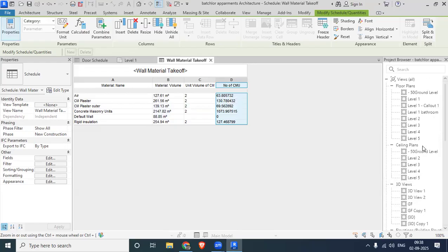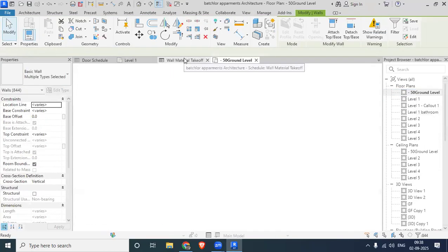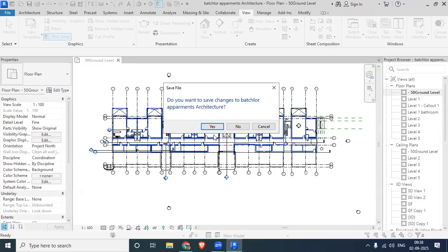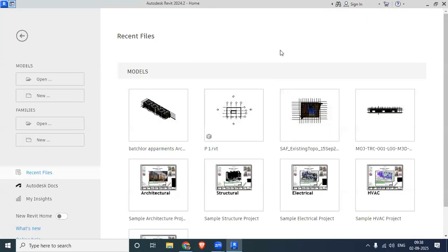All right. I think we have covered most of the parts here. Now let's come down to your families, which we've been thinking of starting. When you talk about families, you have to understand how exactly you can make a particular object parametric.